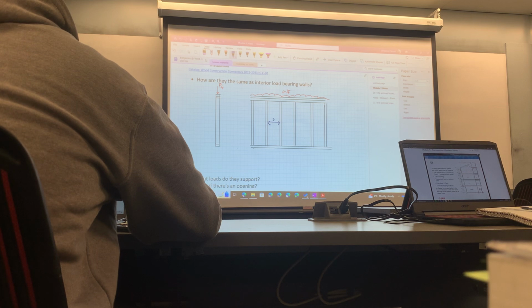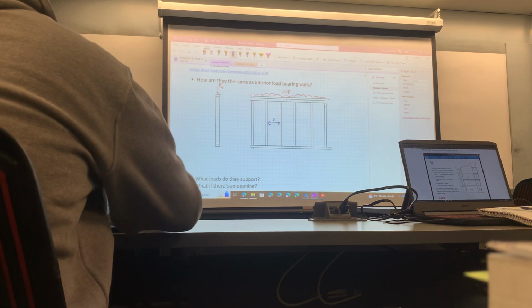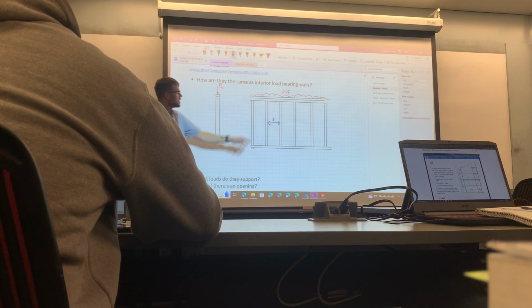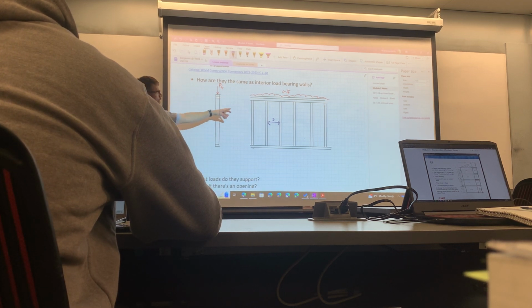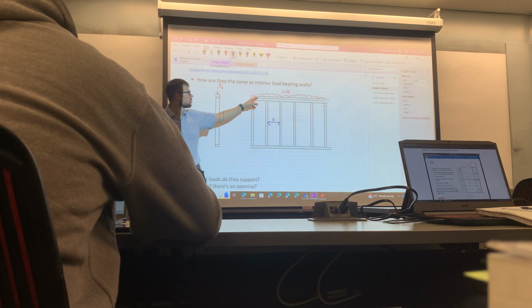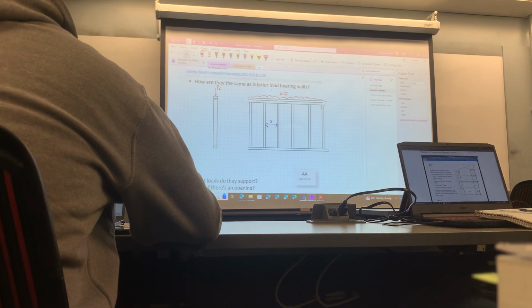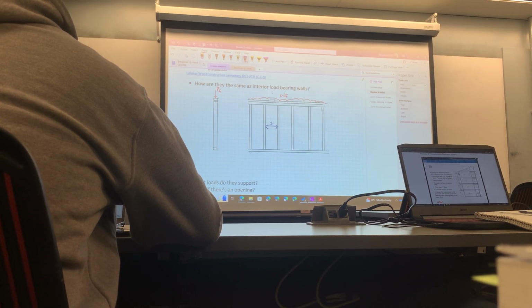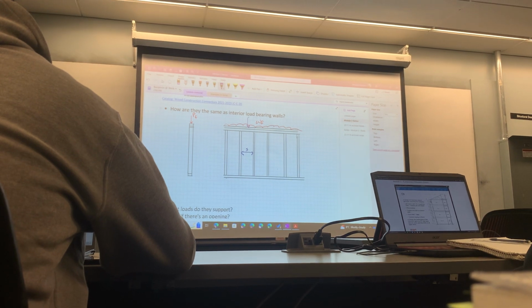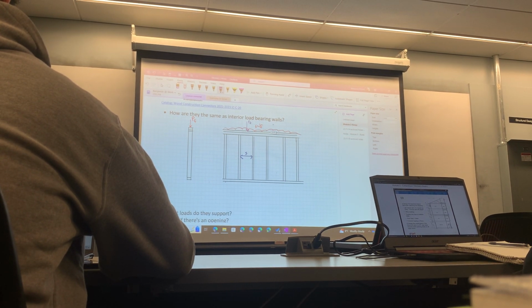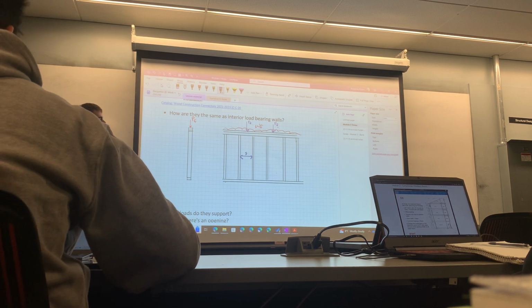There's our spacing. So that's one layer. Everybody, we design these studs similar to how we design columns. We assume it's a concentric load. We derive our axial load from a uniform dead load, a uniform factored load, uniformly distributed load. We also might have some loads from above, which we represent. That could be an opening, for example, coming from above. We talked about openings in example 7.